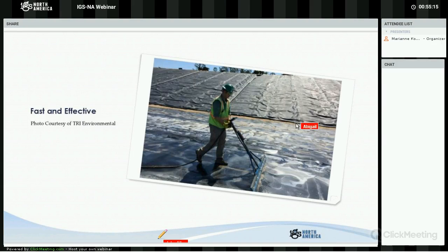If you notice in this photo, there's a brown line kind of on the horizon. This impoundment had all kinds of sediment buildup. In fact, it was probably about 6 inches thick in the deepest part of the sand. And we had no problem doing the water puddle method over huge areas of sand. In fact, I found one leak under about 6 inches of sand because that sand, as long as it's touching a hole, once you get close to the sand and hit it with the water puddle equipment, it will alert you that there's a hole somewhere in that sand covered area. And that's something that the ARC testing method will not do.